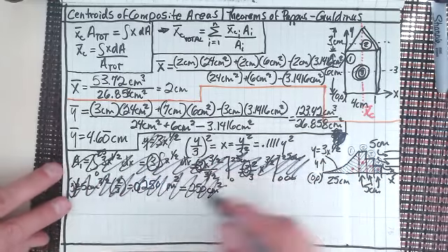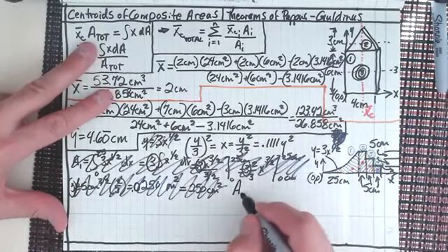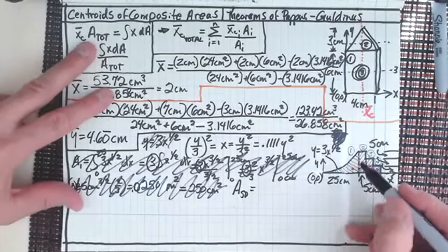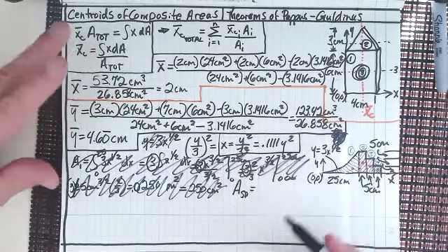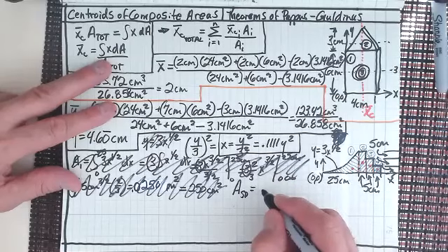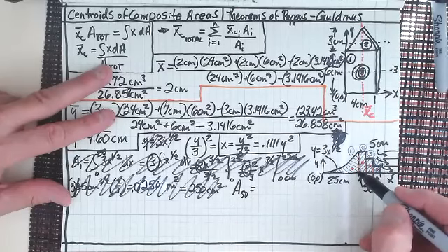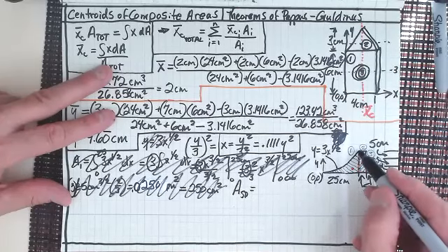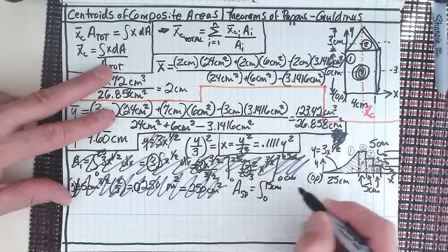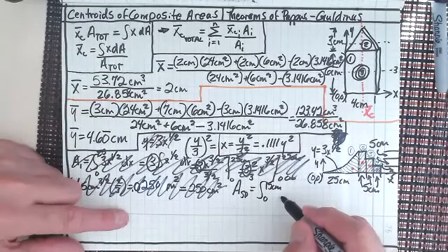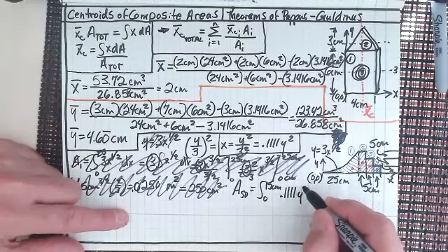There is something obviously here that I'm missing, but what I'm going to do is figure out what the area of the spandrel is, the parabolic spandrel. I'm just going to use the other direction so that I can use this equation right here, x equals 0.111 y squared, and that's still going to give me the thing, because now I'm just going to go from 0 to 15 centimeters, and then I can just use this, which is going to be 0.1111 y squared dy,